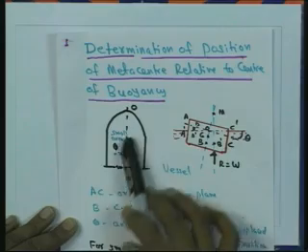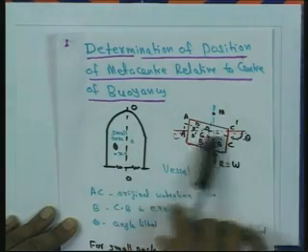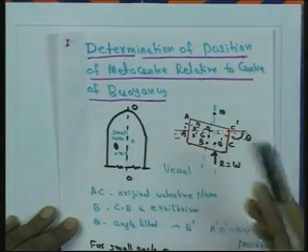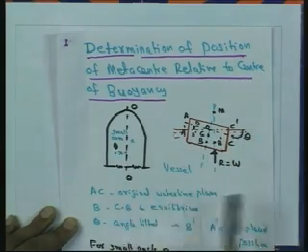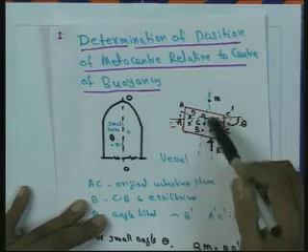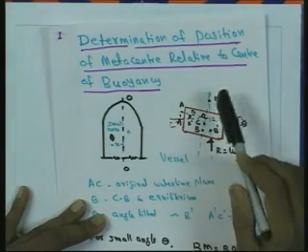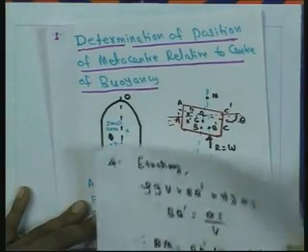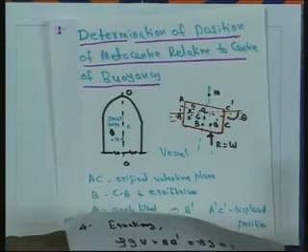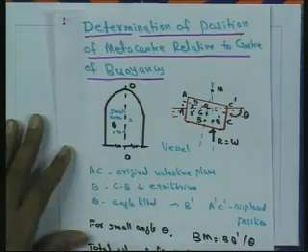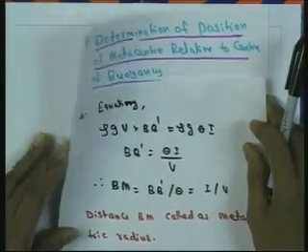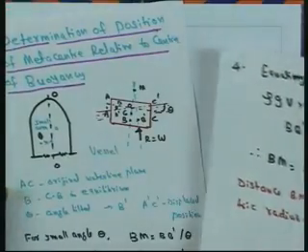What we are doing here is giving a small tilt, and with respect to how much liquid is displaced and the new position, we take the moment, and finally we get this BM, the distance from the center of buoyancy to the metacenter, as the second moment of area of the waterline plane about O divided by the volume of the liquid displaced. That is called the metacentric radius.